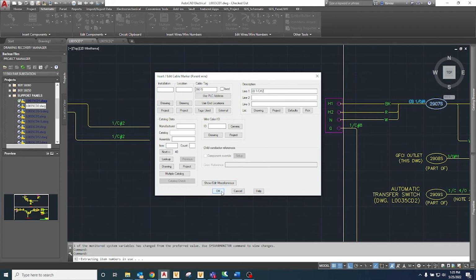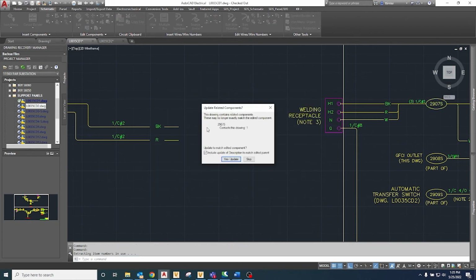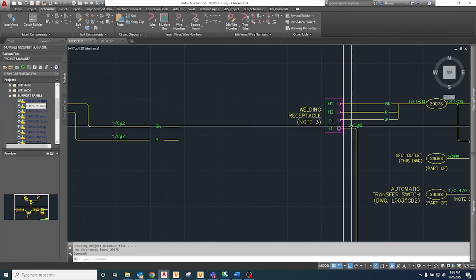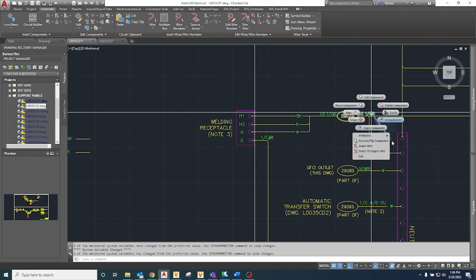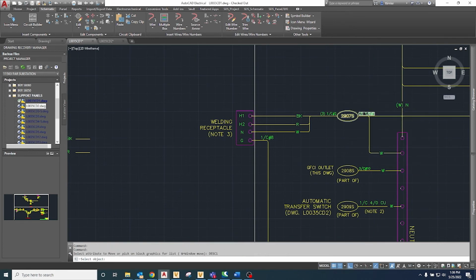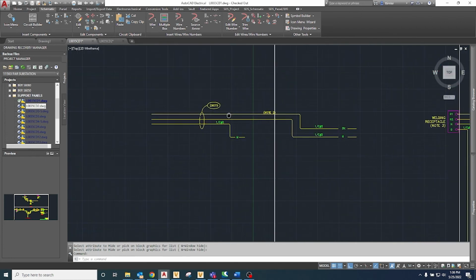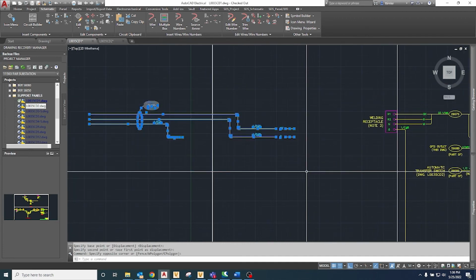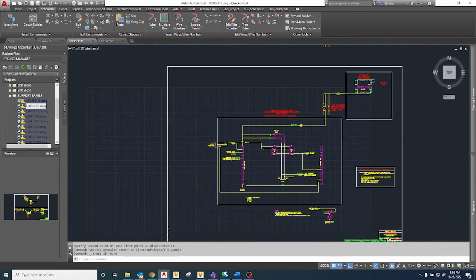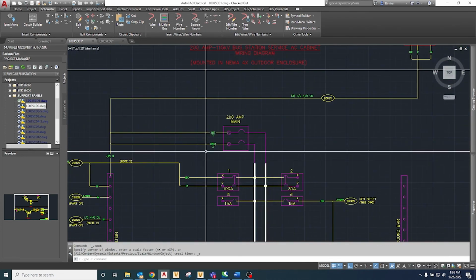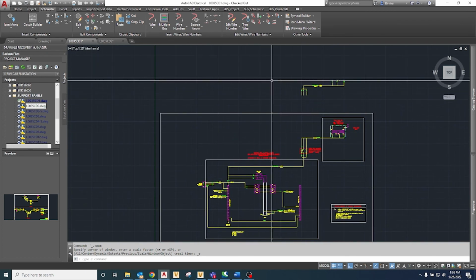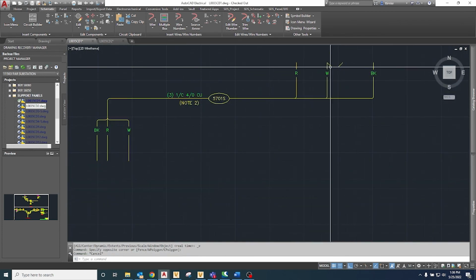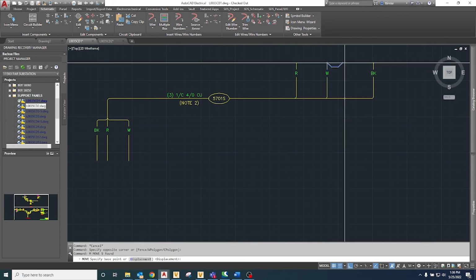Before I delete anything, I'll actually update the cable to the correct cable size. A little tip: to keep track of which end of this cable is the parent and which is the child, I keep the parent description visible so I know which cable bubble I'm grabbing when I use the edit component command. But ultimately, this exercise was about incorporating AutoCAD Electrical and maintaining as much as possible the current look and feel of the customer's current AutoCAD standards.